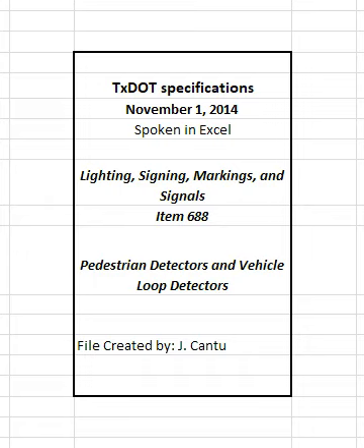2.1 Pedestrian detectors. Supply housing or an adapter, saddle, that conforms to the pole shape, fitting flush to ensure a rigid installation. Supply adapters of the same material and construction as the housing. Supply push-button switches that have single pole, single throw contacts and screw-type terminals and have a design life of at least 1 million operations. Ensure the internal components provide a push-button with normal open contacts, and include all electrical and mechanical parts required for operation.